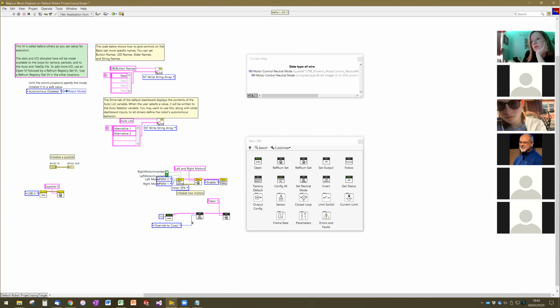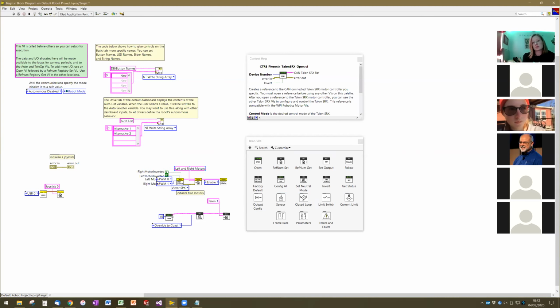So I think, for example, the azimuth motors on the swerve drive are set to brake so that they don't drift too badly, whereas the shooter wheels are set to coast so that when we stop applying a signal to the shooter motors, they don't try to immediately stop and hurt themselves. And of course, there are all sorts of different configuration options that you have for each individual device. In general, you set all those different configuration options in Begin right after you do the open statement.